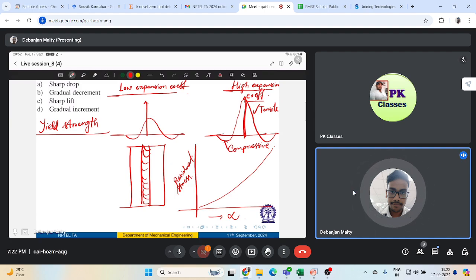So that will cause many issues related to cracking of the weld metal in the heat affected zone. So a low yield strength filler electrode like nickel is sometimes intentionally selected for fusion welding of some highly hardenable metals like cast iron. Cast iron is very hard in nature.